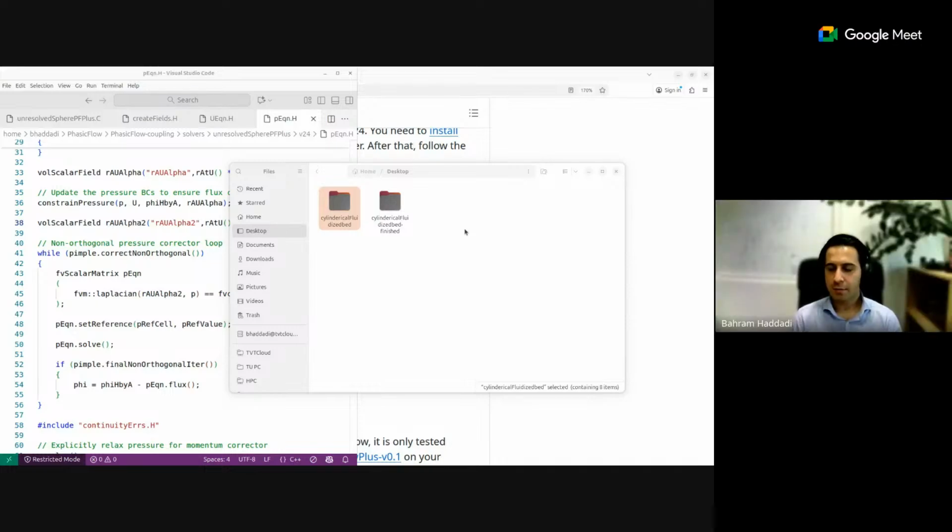Yeah, thank you very much. That was also a very good point. Basically, in the classical Courant number, we are looking at the fluid velocity. But Hamid is definitely right, if we have fluid and particles, then particle velocity also plays an important role there.